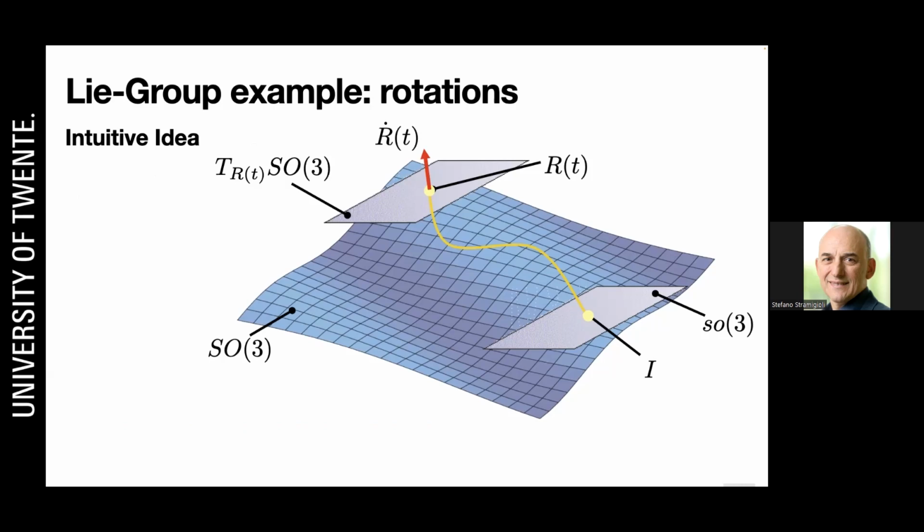But thanks to the fact that it's a Lie group, and by the way, I actually was already wrong, because a rotation matrix is not the configuration. It's something that acts on configuration. I'll come to that later. So if you have this situation, then there is a way you can map that element to the identity. There are actually two ways of doing that, but there are two unique ways to do that. And that is where the omega lives.